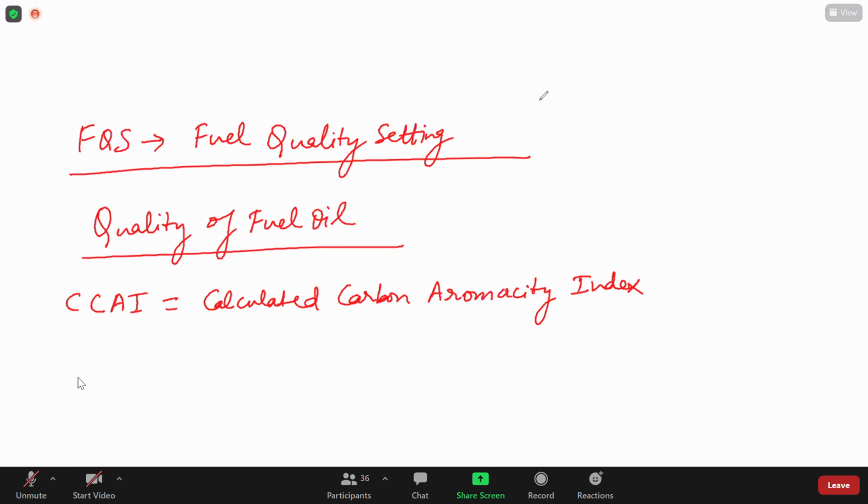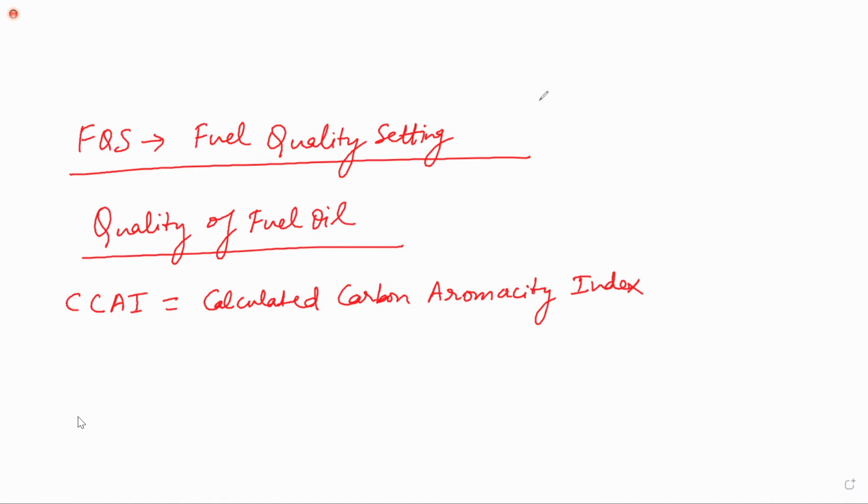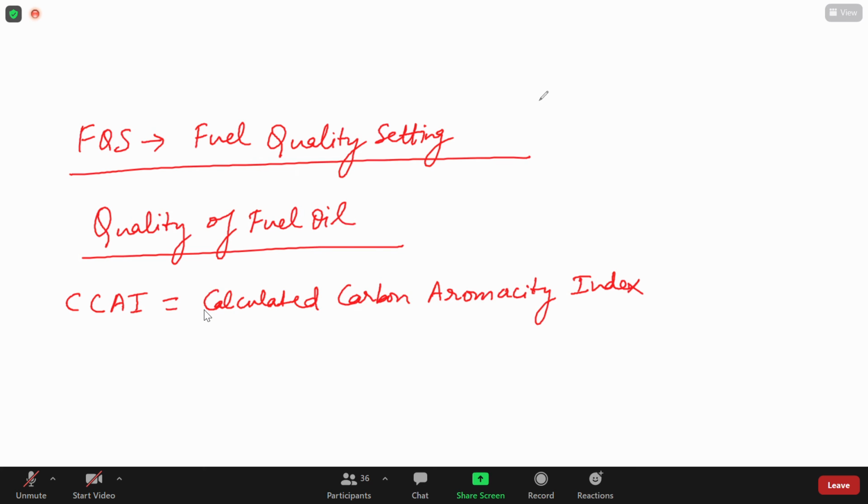Advance कर लेंगे sir. Yes, advancement. Because my injection and ignition gap, जो कि ignition delay बोलते हैं, that has increased. I want the characteristics of the engine, the power generated to remain same. If I don't take action of advancing the fuel injection timing, say by half a degree or 1 degree or whatever is needed, then my ignition will not start at the same point at which I desire it to start.